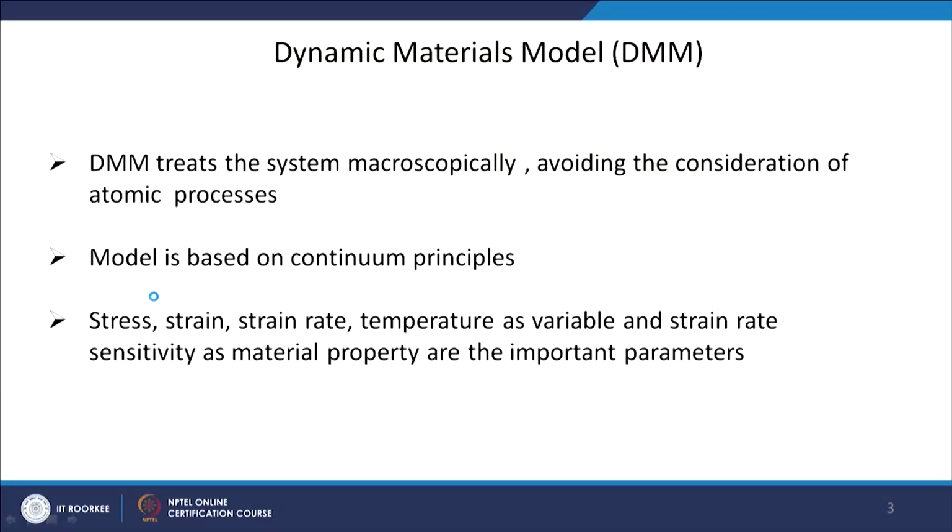So, stress, strain, strain rate, and temperature are variables, and strain rate sensitivity, which is one of the material properties we already discussed, is used to construct the model. So, we are using the continuum principle, not worried about what atomic processes are taking place, and coming up with a macroscopic model.